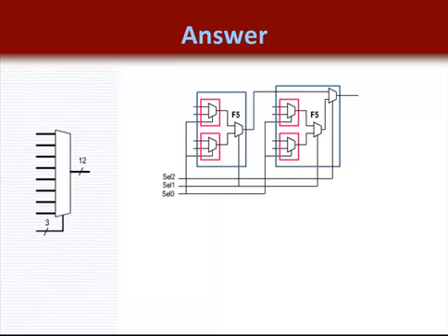Well, the first question, which is the 8-input, 3 select line, 12-bit output multiplexer, can be thought of as being an 8-to-1 MUX replicated 12 times, since it has a 12-bit output. Now recall that the 8-to-1 MUX uses 4 LUTs plus an F5 and an F6, which equals 2 slices. So the entire MUX will be that configuration times 12 for the 12-bit output.